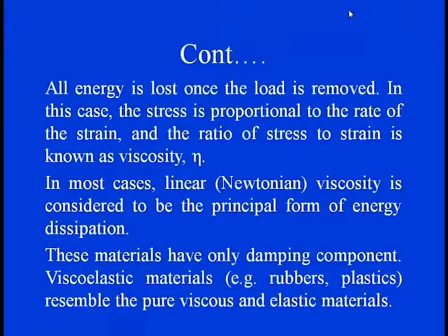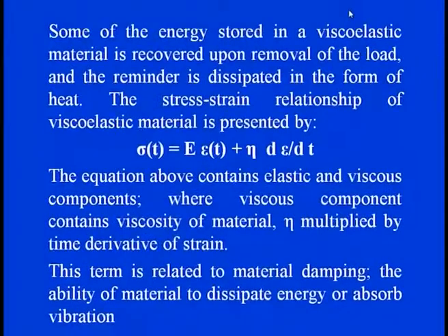Viscoelastic materials like rubber, plastic, or any kind of that resemble both pure viscous and elastic materials, in which both kinds of mechanisms play together and form the entire damping feature. So some of the energy stored in the viscoelastic material is recovered upon the removal of the load, and the remainder is dissipated, transferred in terms of heat.